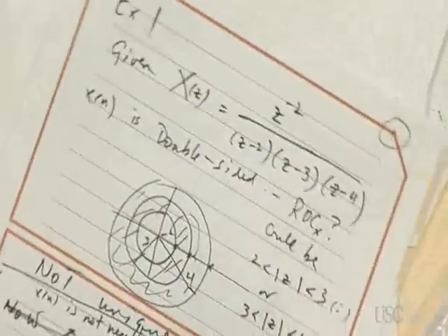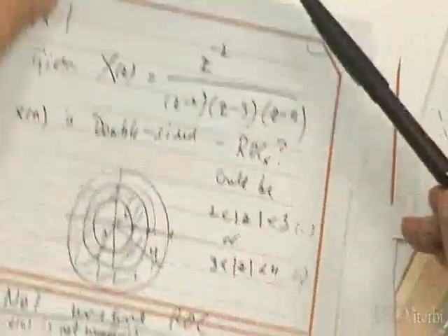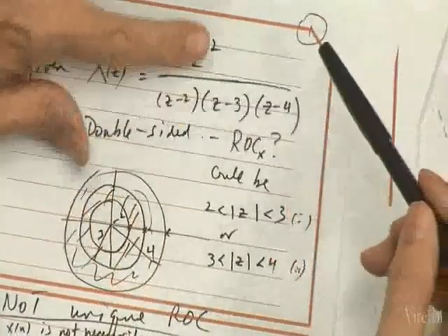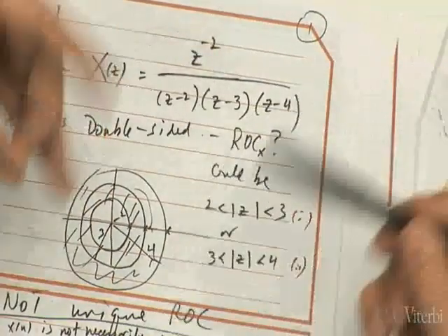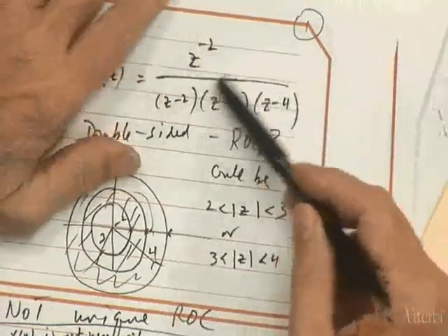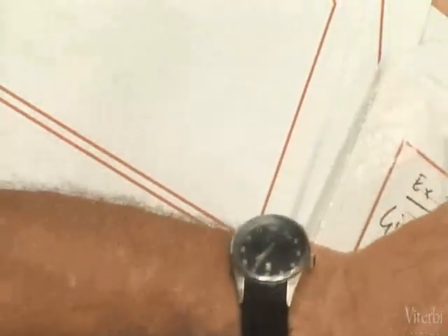Yeah, that's all right. I was just going to say that in this example, there is a power of z to the minus 2, so you can use the trick I talked about before. You can do a partial fraction expansion of just 1 over this, and then once you've got that and solve for the inverse Z transform, you can just shift it by 2 samples. Okay, but I have another example that I found kind of interesting.